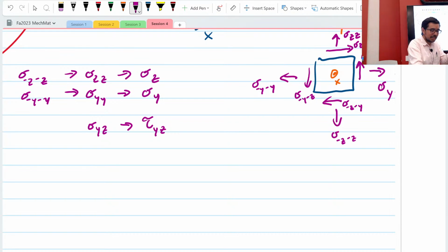Ductile materials fail more easily in shear, whereas for ceramics, the brittle materials, we care more about normal stress. But we can come up with equivalents between these, and we'll do this later in the class. Essentially, it fails in shear, and that's circular reasoning for now. And if we got into the molecular level, we could say there's some sliding of the grain boundaries and stuff, and that allows us to get this easier failure.